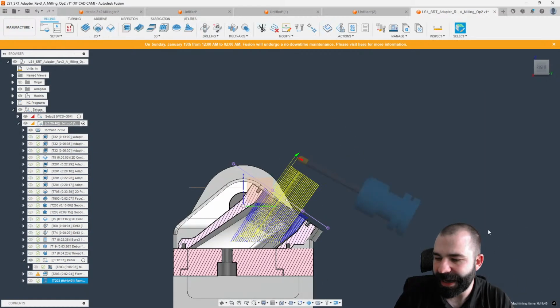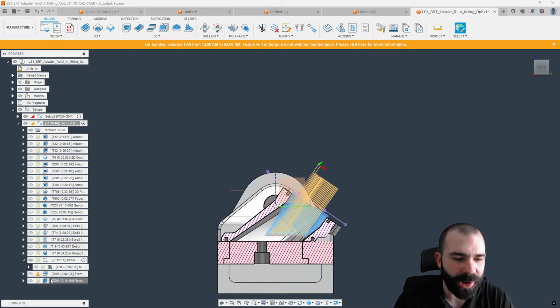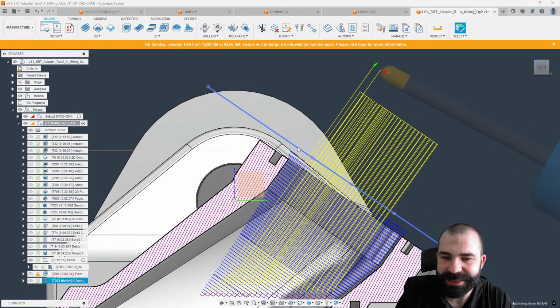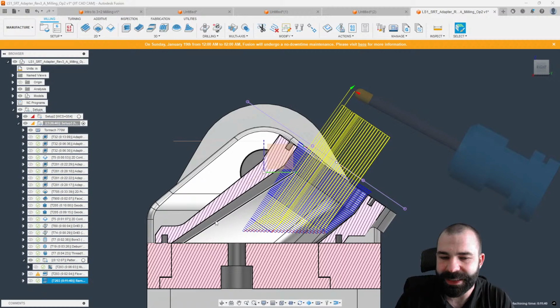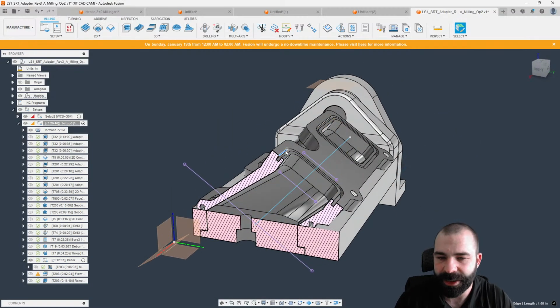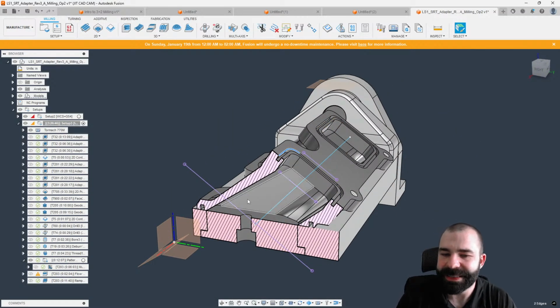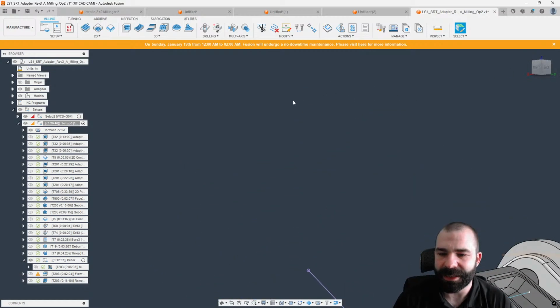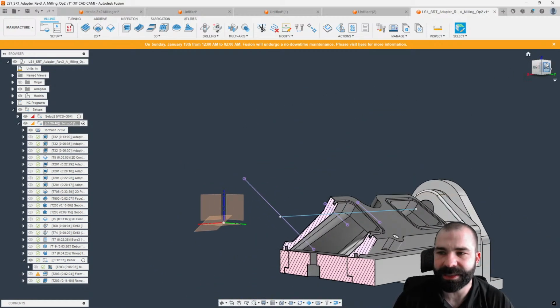Now, something I am recognizing on this specific profile, and we're going to ignore the tilting real quick, is odds are we're probably not able to get underneath here, because if you remember the projection of our boundary, right? We picked this outermost edge right here, so odds are it's not allowing it to get underneath here, or it's being limited by undercutting, right? So this is where we may need to, once again, do a few little things to this part to get a little better result.